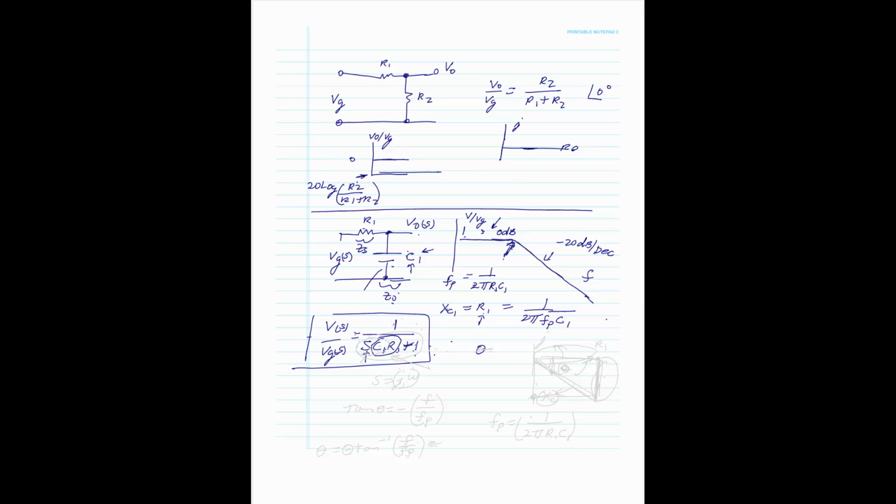You can see that the phase here is going to be the angle of this. But you've got to understand that this is an angle on the bottom. You know, s is j omega. So you could see this s is on the bottom. And if we flip it to the top, you're going to have to multiply top and bottom by what's called a complex conjugate, and you're going to get a negative j term on top. So in reality, this phase is an angle whose R1 is the real, and you're going to have this omega, this point here, as being your X sub C.